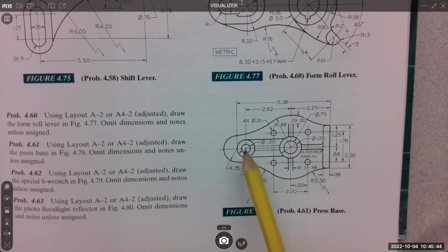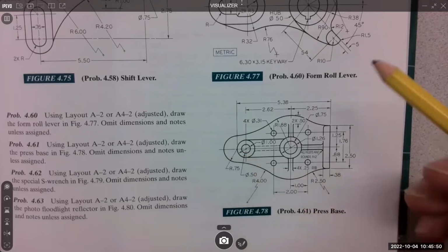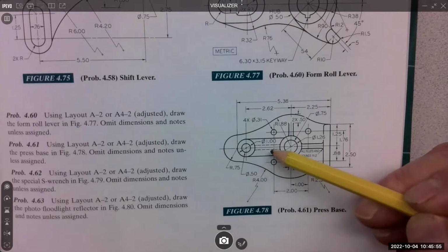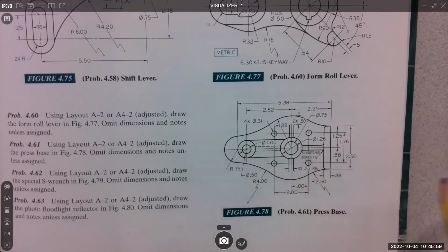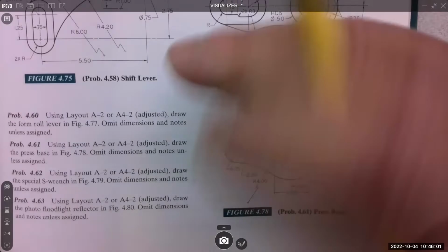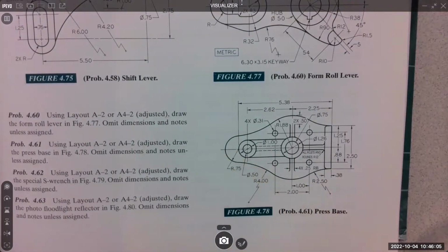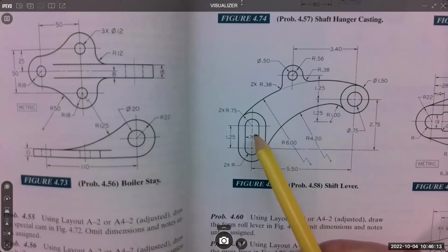And you can see some center lines here. Oh, there's a thin phantom. Yeah, I don't know why they did that. Oh, it's a double mark. So that's marking here. Could be just a general symmetry line, maybe. Everything's symmetrical about that, right? So that could be a symmetry line. Does the center line have to have 2 dashes on it? Or can it be just a single dash? Center lines are single. Yeah. So the 2 dash there, I think is a symmetry line, but here's a typical center line.